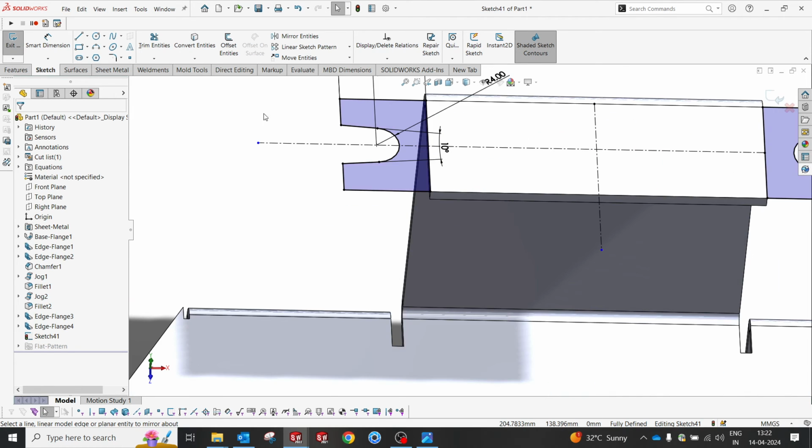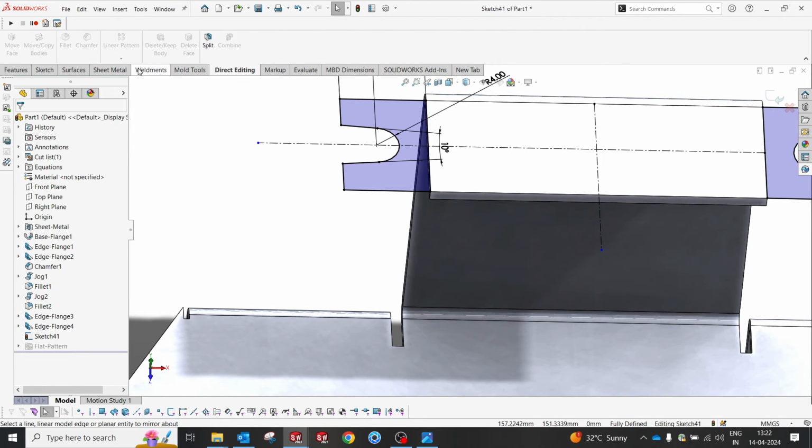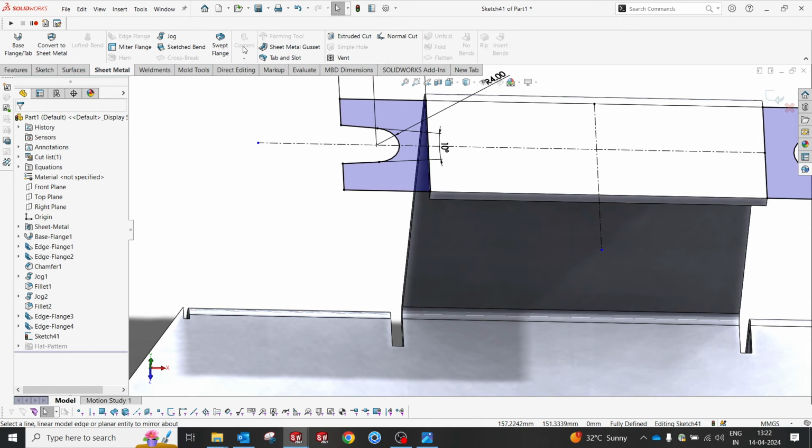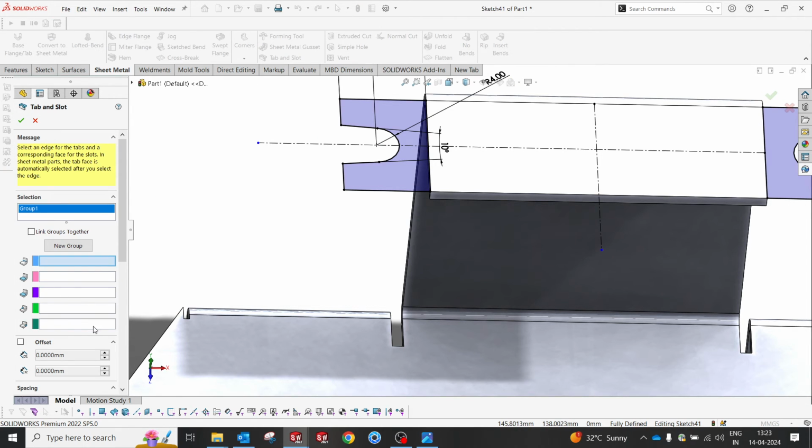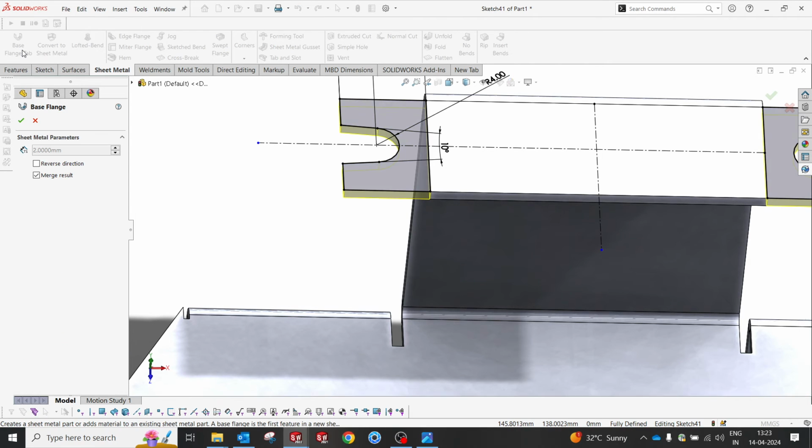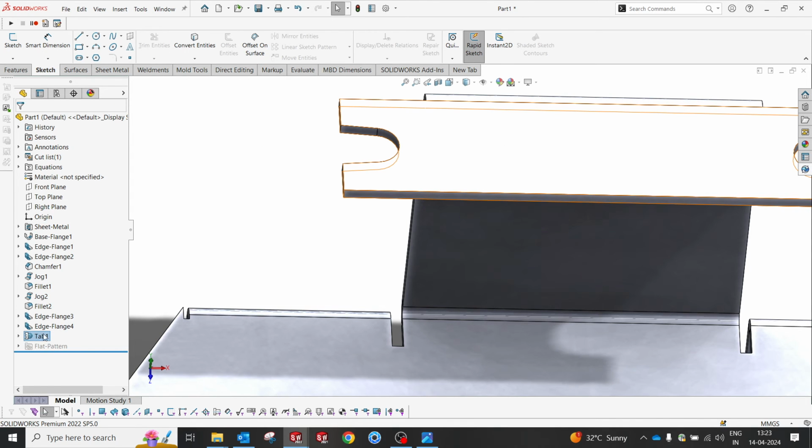So now you can select, there's no option for a tab or something like this. But again, if you go for emboss extrude, it may be there. But let's see, we're going with this option, and there's nothing much to do with the slot. So I'm just going to create this as a 2, so the same tab will get generated with the option.